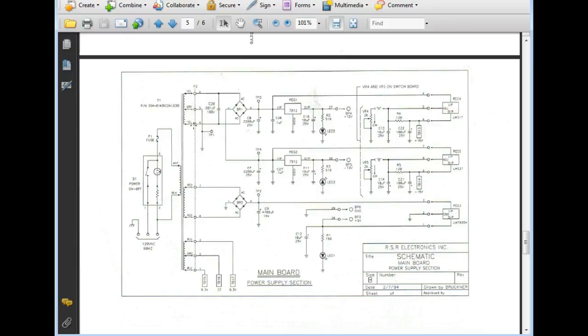You ever run across situations with both primary and secondary fused? Yeah, I have. I'll give you all the procedure. It's in the NEC National Electrical Code book that shows you how to calculate the fuse for the secondary and the primary. But you actually overfuse them because of a lot of things that go on, plus things that happen on the power lines and stuff like that.